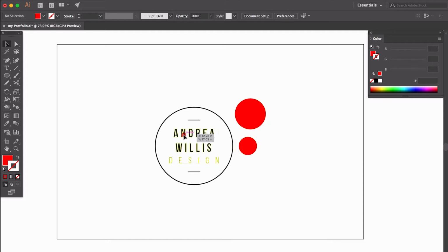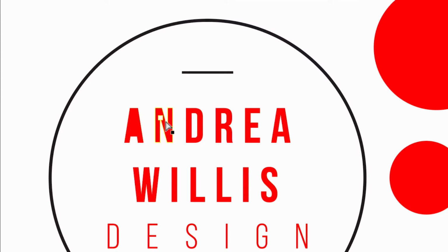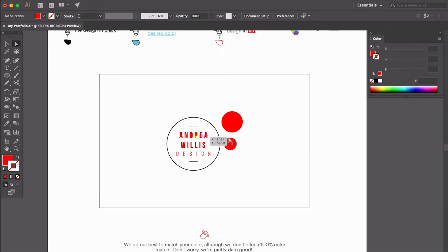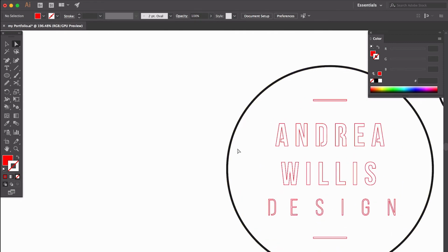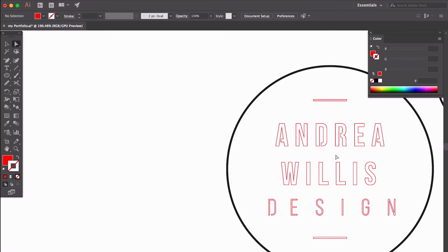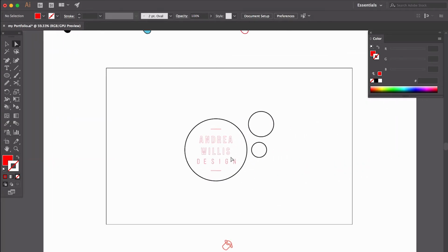If I want to cut out this text, the center of closed shaped letters will also fall away since there won't be any surrounding material to hold them up. This goes for closed shaped letters such as A, B, D, O, P, Q, and R. One solution is to create breaks in your design so that they're not closed shapes, or engrave it instead. All right, your design is ready to go with a cutout treatment.